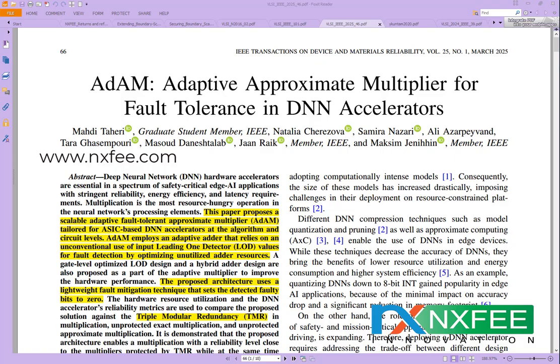A leading one detector is designed in this paper to generate both the positions and the logarithmic value directly, reducing redundant computations. The parallel shifter is remodified with adaptive truncations, which lower area and delay. Addition is performed by hybrid parallel prefix adders, where Brent-Kung is used for the LSB and Kogge-Stone is used for the MSB, the most significant bits. It achieves higher speed and balanced area compared to the traditional triple carry adder method.